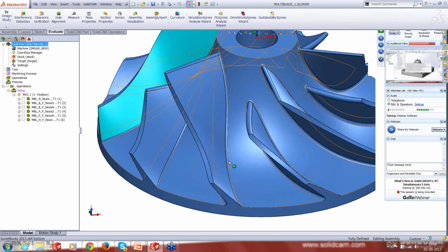You don't need more than that. Once it knows that this is the hub, it does the revolve internally. But the only thing that you need to make sure when you're defining a surface for either shroud or hub is that there should be a surface formed from surface of revolution. There can't be some NURBS patch. You might end up with some errors if you are selecting a NURBS patch, but generally they are not because impellers generally are done using a revolved surface. But to answer your question, there would be no difference.